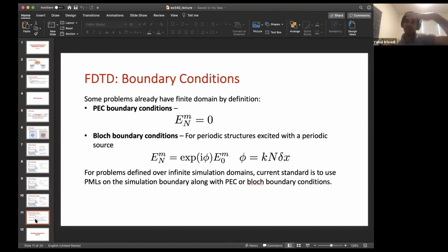And absorbing materials exponentially damp the field inside the material. So if you put in an absorbing material, the fields inside it will exponentially decay. At some point they'll become quite small, and then you can put some other boundary condition like a radiation boundary condition, or you can even just put a perfect electrical boundary condition, because your field would have gone to zero because of the exponential decay in your problem.